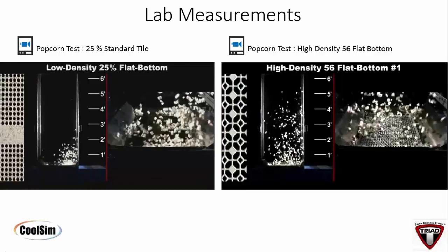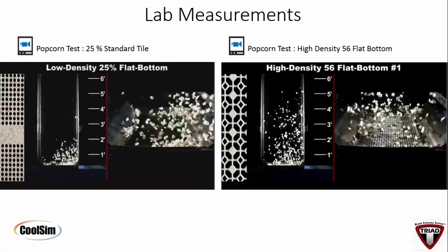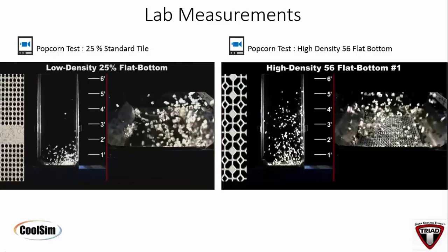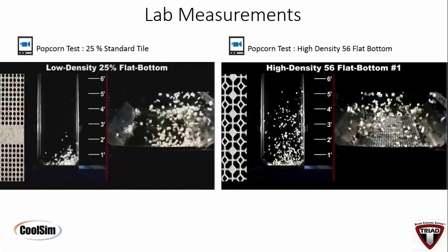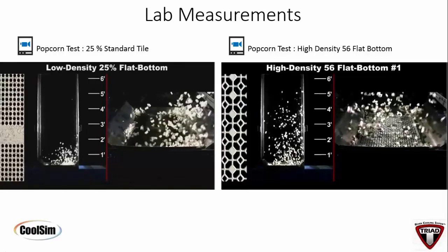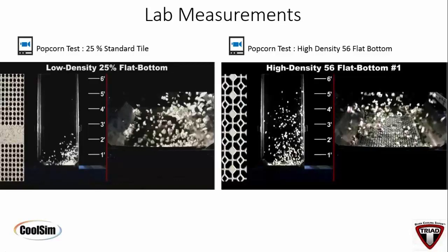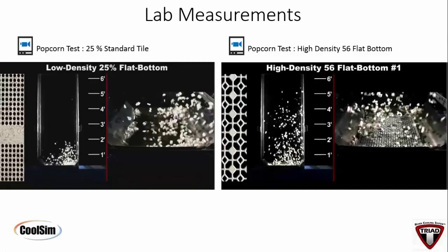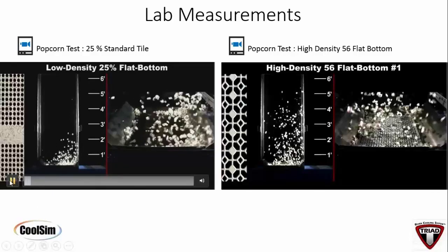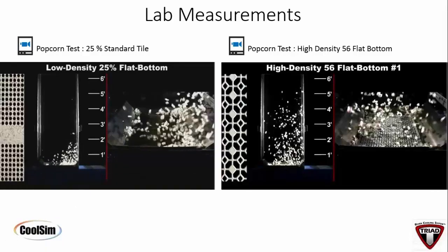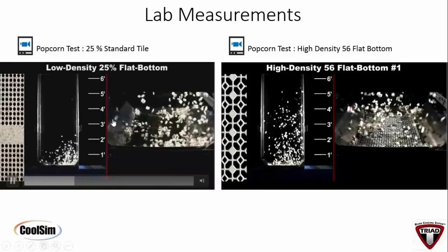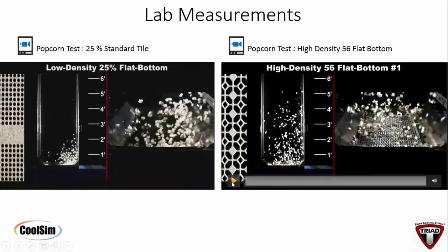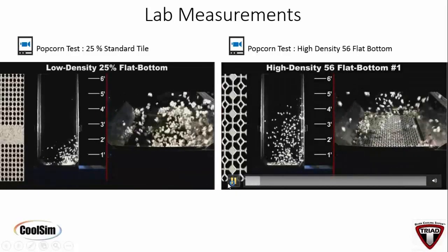Right, yeah. We went from the streamers, and we tried smoke, but that dissipates too rapidly to really see what's happening with the turbulence or the flow. And that's what we were looking at: if we had plenty of cold air, why aren't we getting better cooling efficiency through the server rack? With the popcorn, you can actually see that front draw down. It's a short cycle effect, right, even though you're getting flow at the back end of it. So this effect on the leading edge is something we'll... You're seeing the same stratification. Yep. And over here is the 56%er, right?